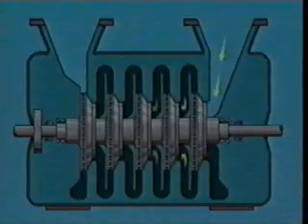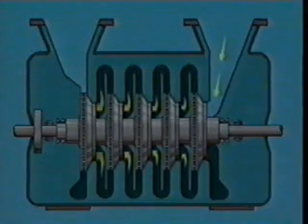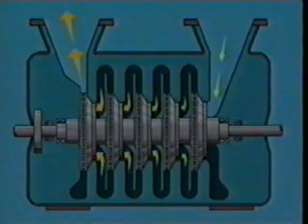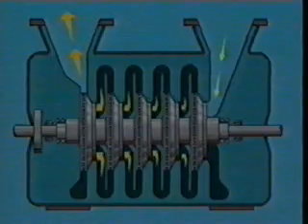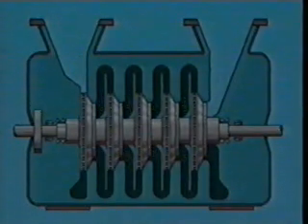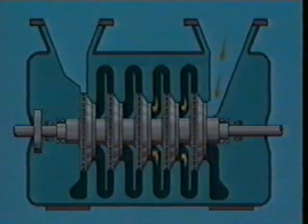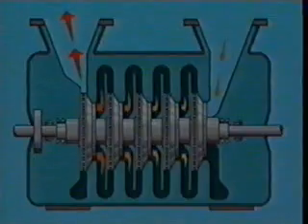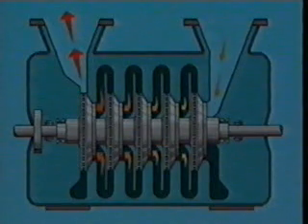While surge is occurring, the gas is recirculated through the compressor and becomes heated by the compression process. As the gas recirculates back to the impeller into lower pressure, it retains that heat. As it is recompressed to its original high pressure, additional heating takes place. If this is allowed to continue unchecked, the gas will become hot enough to cause a bearing or seal failure.